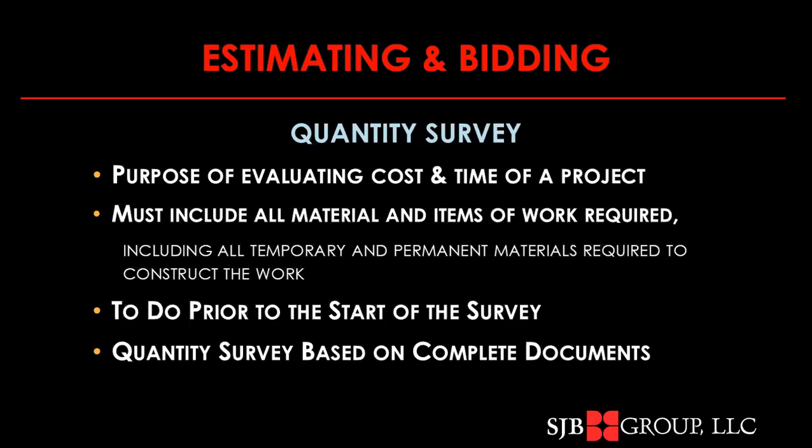You're going to review the following: a breakdown of the price. You're going to look at alternative prices. You need to determine whether pay items are unit price or lump sum. You're going to need to develop a bill of materials as you do your takeoff. There are some special rules of measurement for payment of certain items that may be different than the way you would want or think about, as provided in the contract.